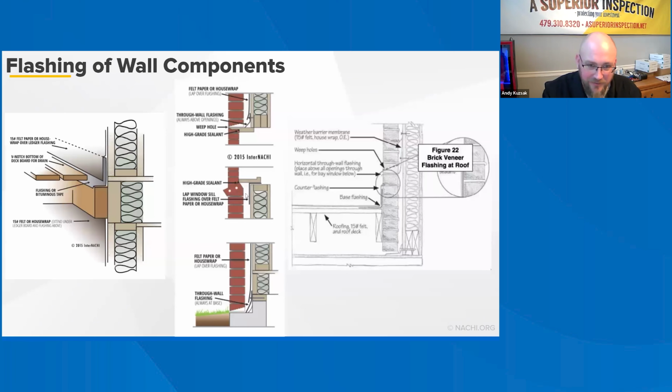And so I carry around a little level with me. If there is any question about whether the brick is pitched towards the outside or towards the inside, we'll put the little level on there and make sure it is pitched out. If it's not, we call it out and recommend to the client, if it's new construction, that the builder address it. If it's existing construction, then it's up to the homeowner.